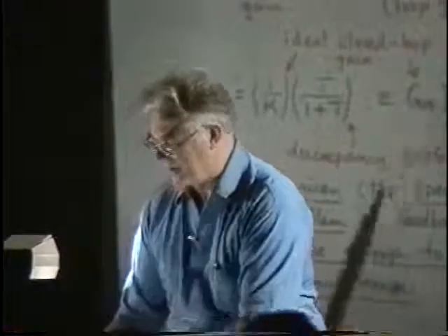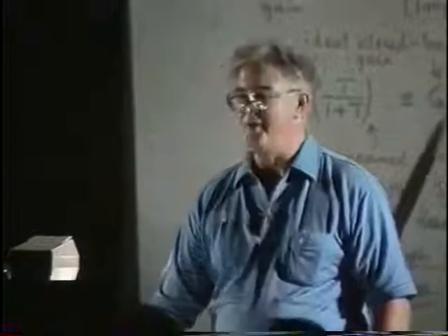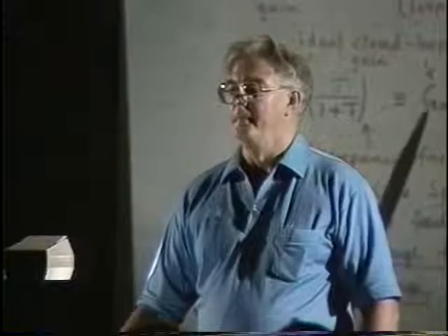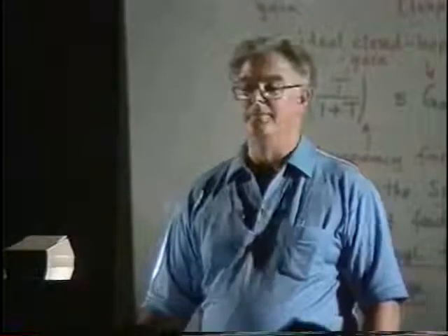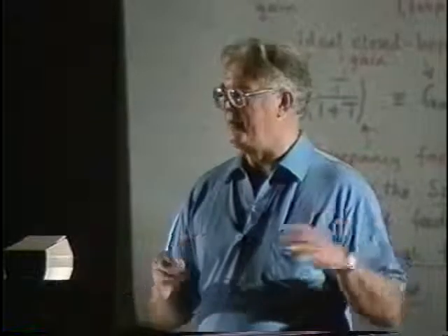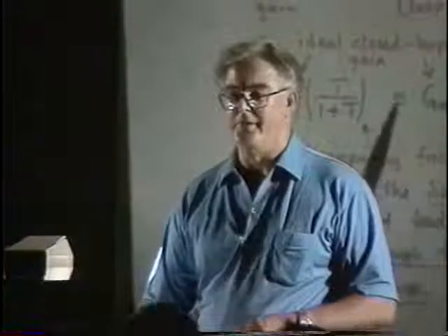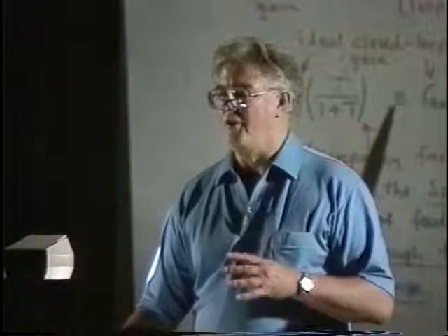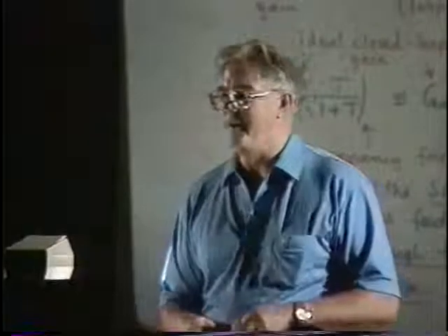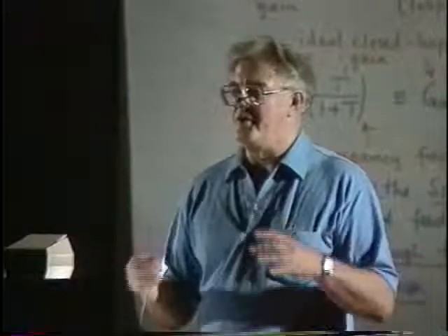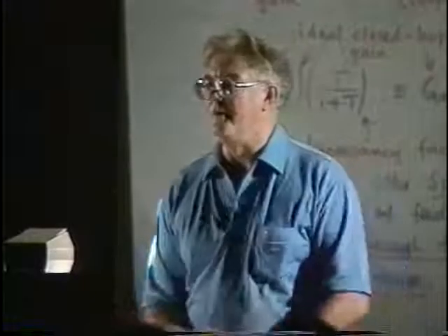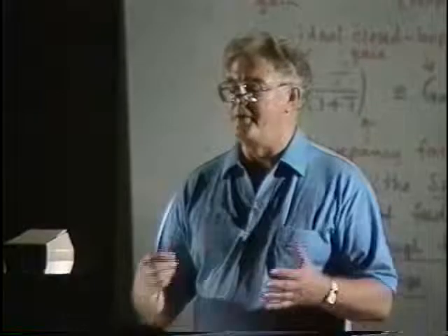Well, the next couple of pages are to do with how you calculate the G infinity, and I'll skip those because that's what you ordinarily do anyway. You simply assume zero error signal, which allows you to match the feedback signal directly with the input, and that's how you get the G. The only difference from what you normally do is to recognize that when you've done that, you have actually calculated G infinity, not G, because you assumed zero error signal, and assuming zero error signal is equivalent to assuming infinite T. So that's the only difference.